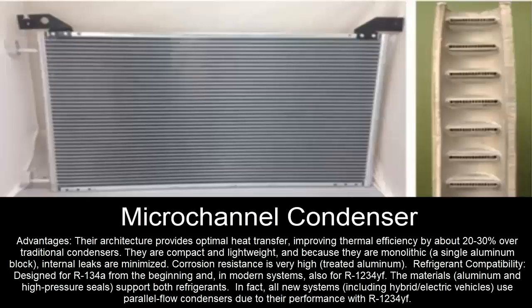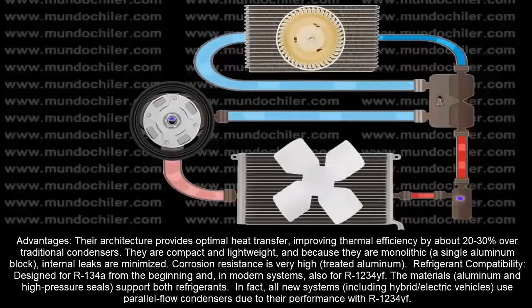Refrigerant compatibility. Designed for R134A from the beginning, and in modern systems also for R1234YF. The materials, aluminum and high-pressure seals, support both refrigerants. In fact, all new systems, including hybrid and electric vehicles, use parallel flow condensers due to their performance with R1234YF.